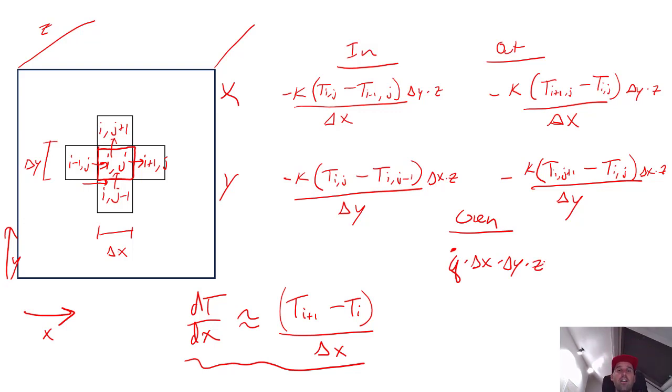All right, so we've got our energy balance. So we have our accumulation equals in minus out plus generation. When we first plug this in, we're going to assume generation to be 0, but we can have certain nodes that might have generation, which we'll toy around with here in a minute.